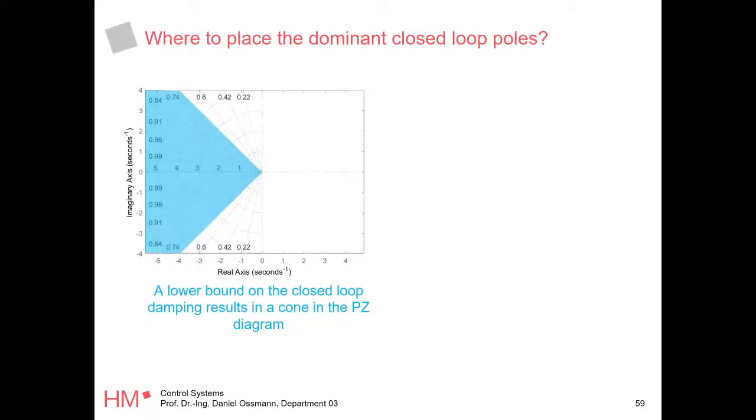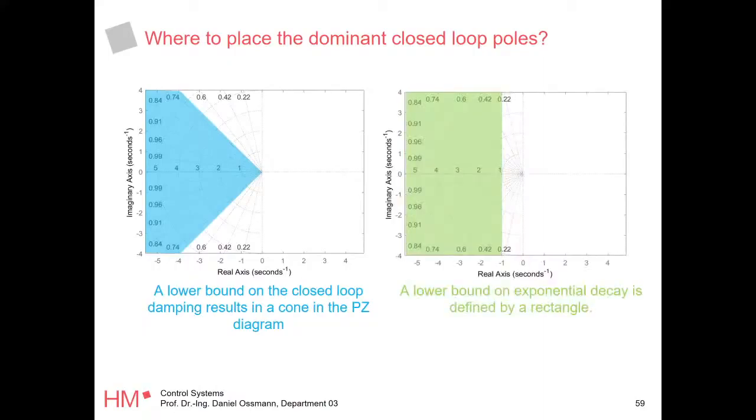Okay. Often what you're going to say is, I want to have a minimum on my decay time, right? And remember, what does a pole have? A pole always has a real part, right? So P1, 2 has a real part and an imaginary part. And this real part shows up in your exponential function, right?